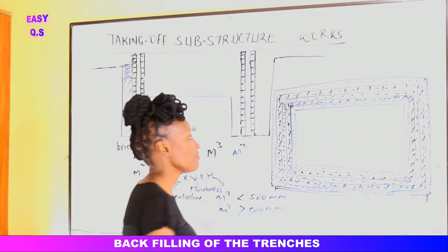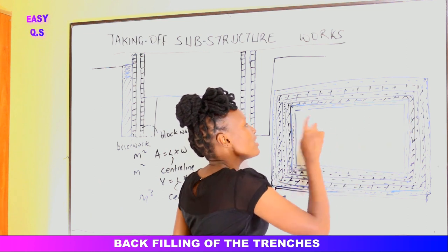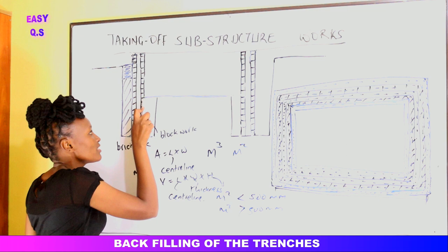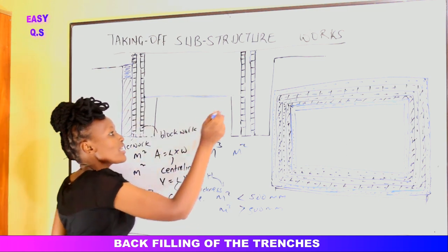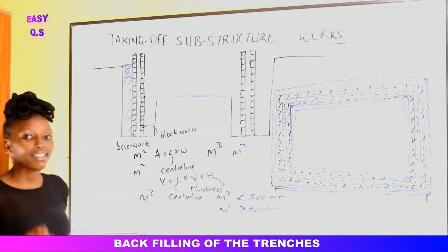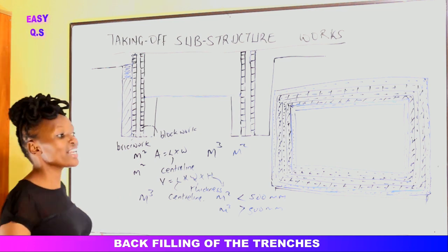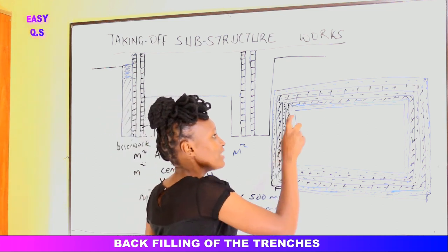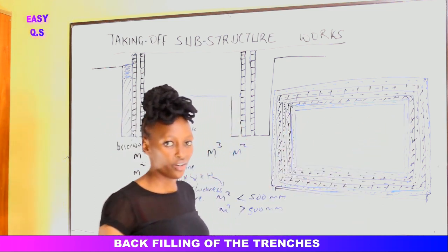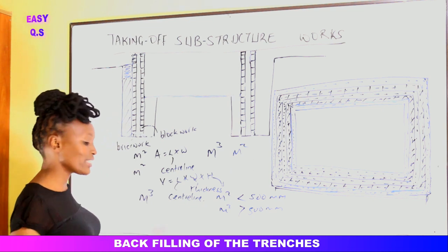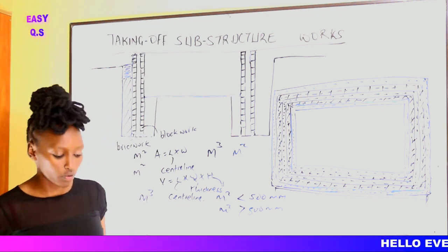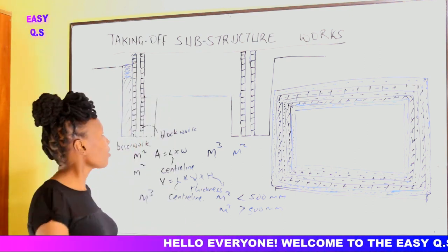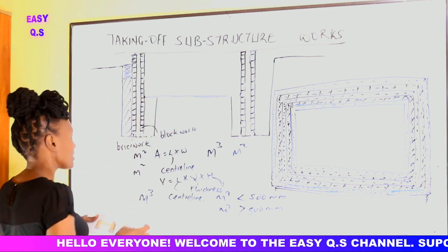So all this area shall be compacted. So this area shall be the length from here to here, the width from here to here, because all that area from the surface of the wall on the inside, the internal wall, we shall take length times width. Alright, so the next item after compacting the ground, we need to fill to make up the levels with hard core. After compacting, we just need to do some hard core.